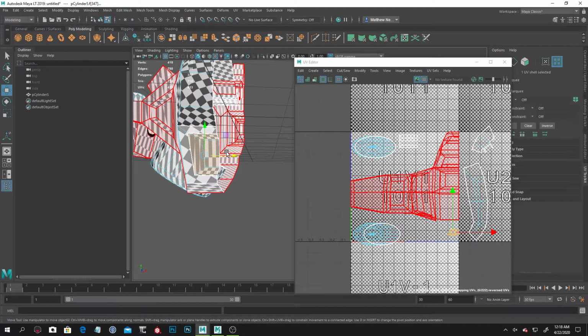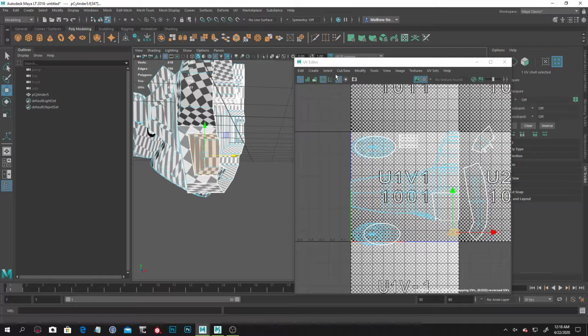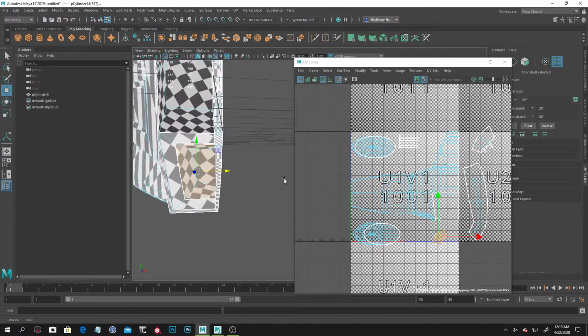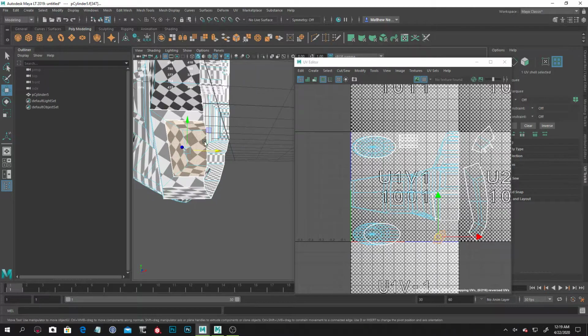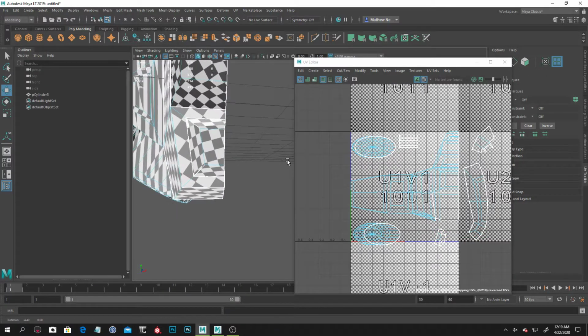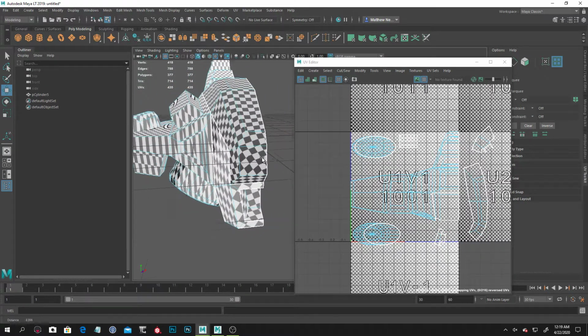This interior part, that's its own piece. We can go ahead and stretch that out. So I can go Control U. Hold on. There we go. Control U. Now you'll see that one didn't stretch great because I didn't make any cuts into the model to help it unfold a little bit better. And you can do that by just coming in, clicking some edges, making some cuts. And then we'll go back to selecting that particular shell, Control U. There you go. That smooths it out. You want to get this nice checker pattern wherever you're at.